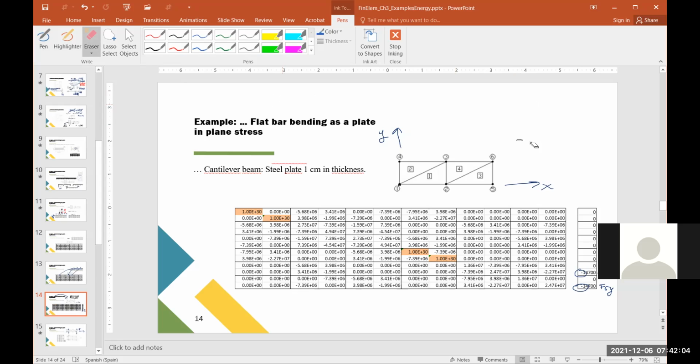So that's something very important with finite elements, okay? Remember, you all studied this, for example, we could use finite differences. If we want to partition this, in this case, for example, if we want to include this as the dimension, then we have to make it like this. So this is our system. Why? Because we can only use quadrilateral partitions. With finite elements, we have flexibility.